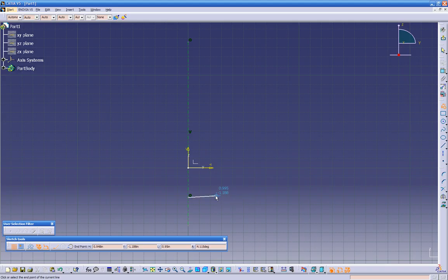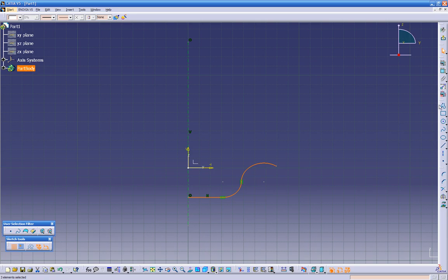See this right here? Every time you open it, this profile always goes in a straight line. Then you can create your arc. But what we can do, instead of starting with a straight line, we can start with an arc from the beginning. So what we can do is cancel this, and we're gonna go here. Let's cancel this. Click the delete key.